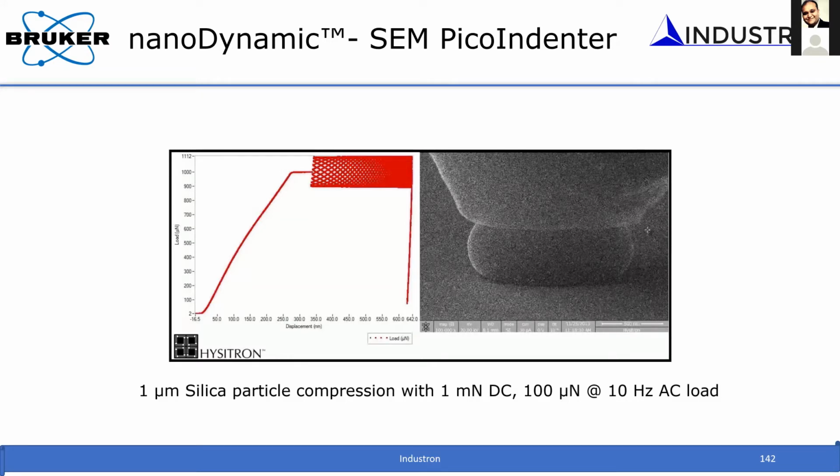So the electron beam induces some kind of a deformation mechanism within the material that allows the material to be highly plastic. So one clue is that we can use this technique if you wanted to shape brittle glass materials like silica. You can do a high plastic deformation in the presence of SEM, an electron beam, to any shape that you want. Okay, so this is a pretty nice example.